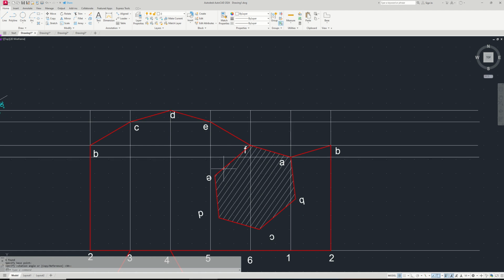Points are matching, but the truncated top part is lying on the development of the vertical parts. That doesn't look nice. I don't want to have that. So to see all my parts carefully, development of vertical part, development of top, development of bottom part, I want to flip this outside of the development of the vertical parts. I'll flip it by using the mirror command.